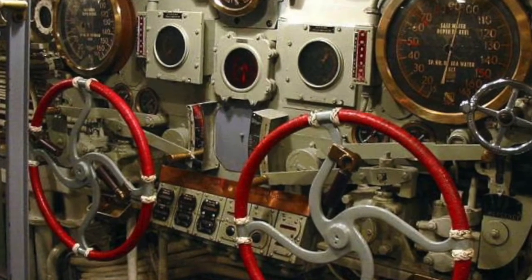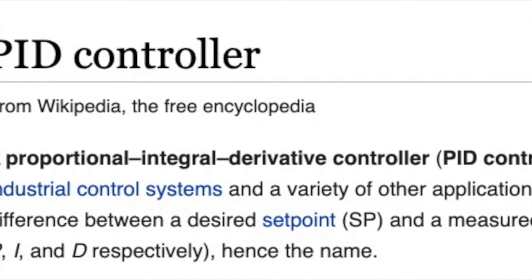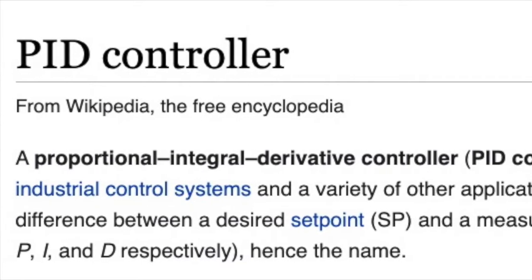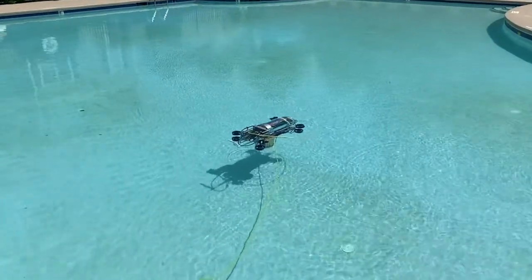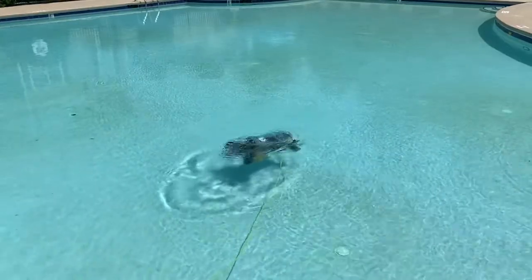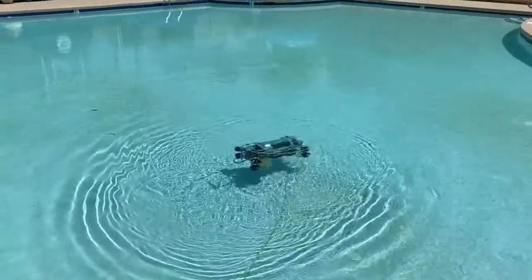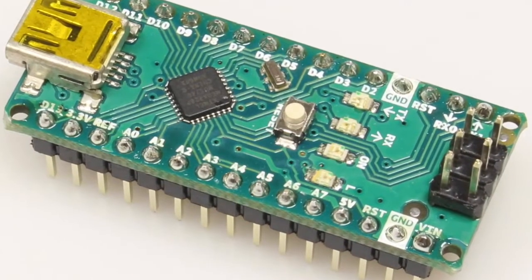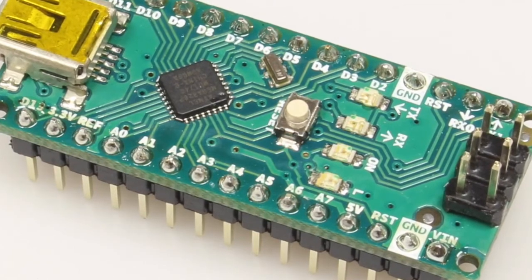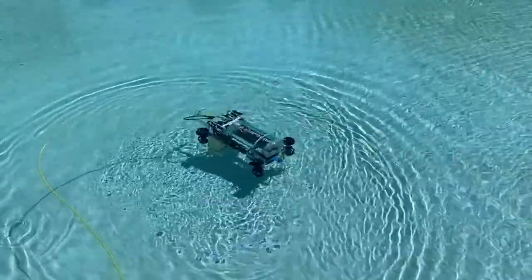Lastly, our controls software design. Our controls algorithm is based on PID, proportional integrative derivative loops. When our task planning code tells us we need to go to a certain point, our PID loops allocate power to the thrusters by calculating whether we are on course to reach that point using our sensor data. If we are off course, our PID loops automatically tell the Arduino to adjust. In this way, our robot control is reliable and fully autonomous.